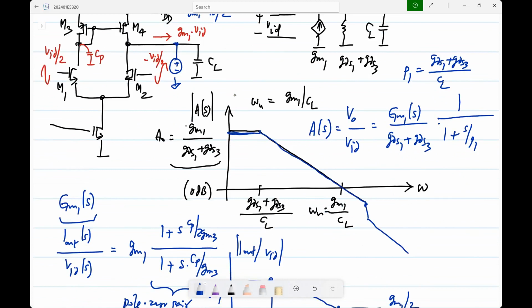So you will also have to get comfortable with estimating these things. If you just want to put all the quantities in the circuit and calculate, you can do it probably with a symbolic calculator, but then you can't make sense. So you have to also know, that is the engineering that you learn, when to neglect GDS, when to include it, and so on, because that's what I've been doing.